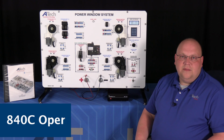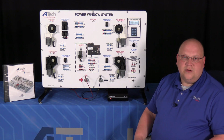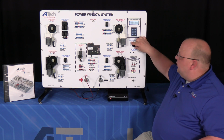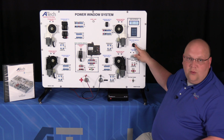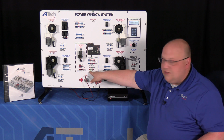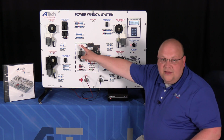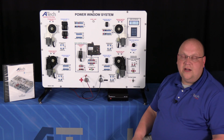With everything powered up, let's cover how we turn this thing on and see how we can operate our power windows with this. The first step here is to do our ignition switch. We're going to move it all the way to the start position and then bring it back to the run position. That's really important that you bring it back to the run position. You'll notice that in the run position, the LEDs for the power window fuse and the accessory relay come on. That's really important that those LEDs are illuminated, otherwise the unit's not going to operate properly.